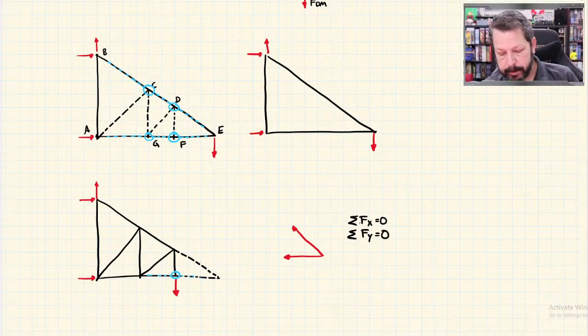Because the horizontal one has no y component, when I write my y equation, the one that's at an angle says that one's a 0 value. But then once it's a 0 value, it has no x component. And so the summation of forces in x says that the one that's horizontal has to also be 0.